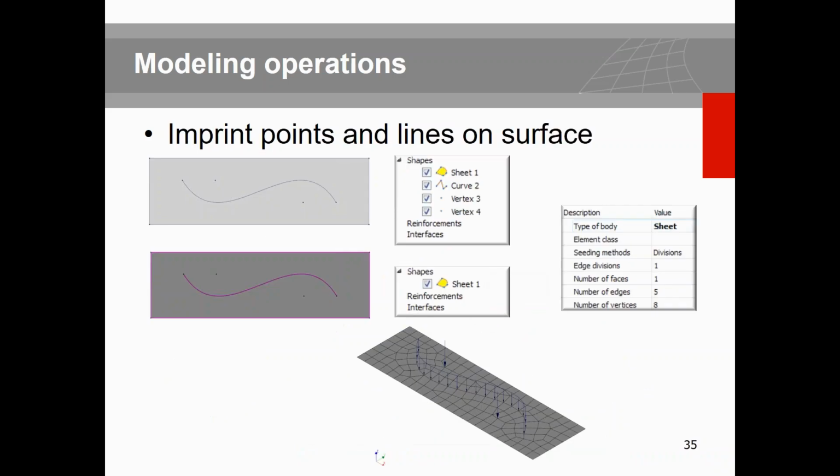In order to define the load or boundary condition, there is one important factor that you need to consider: you always need to imprint the position of your load or boundary in your model. Imagine from the top, if you look, this is one panel of the slab, and you have a kind of curved distributed load or edge load, as you can see in the final configuration, and 2 point loads.